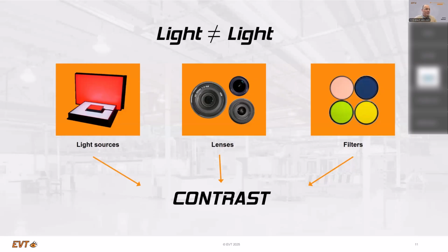In this case, of course, you have to think about maybe a light source which uses UV light, because most of the standard cameras, which I mentioned before, which can see the full spectrum of the human eye, also have the option to see in the UV spectrum. And then you can use a UV LED, or any other light, but mostly today it's LED lights. And then with the combination of a fitting daylight cut filter, you eliminate for the camera all the daylight spectrum, and you only pass the UV light.